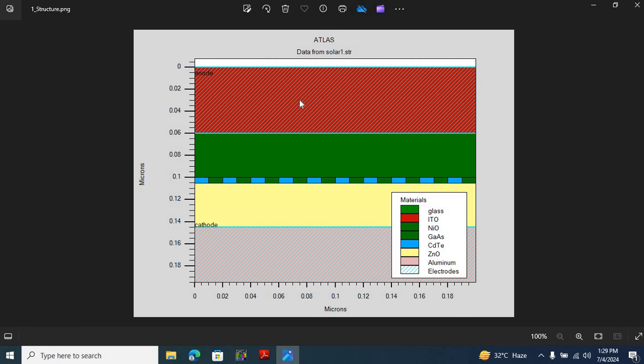And so here is my structure. It comprises a transparent conductive layer, which I've assigned as an anode, followed by a nickel oxide hole transport layer. After that I've introduced quantum dots inside this structure, followed by the zinc oxide electron transport layer, and finally I have employed aluminum as a cathode layer. So let us start with the basics.